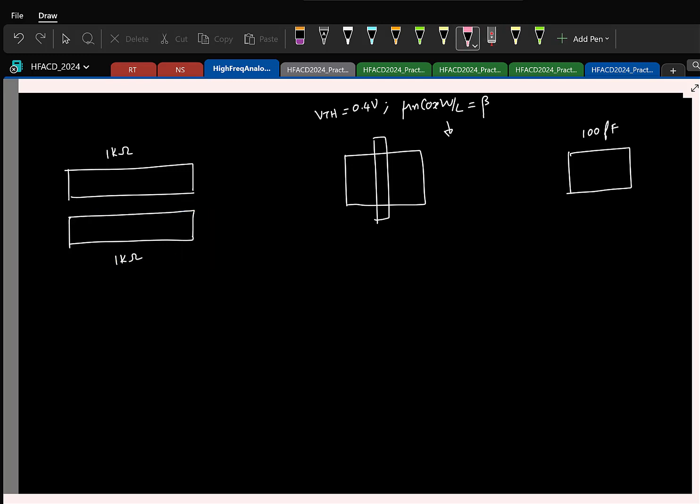Again, one simple way to understand this: here I have drawn nice rectangles for the resistor, but in practice you can't etch out rectangles. You will have a lot of rugged edges like this. So you'll have something similar happening here also, but you can't guarantee that what's happening for the top resistor will happen exactly for the bottom resistor. So you'll have variations in the resistor value. Now let us say I have 1000 such identical resistors in my design. If I find the value of all the resistors, they will be slightly different from each other, right?